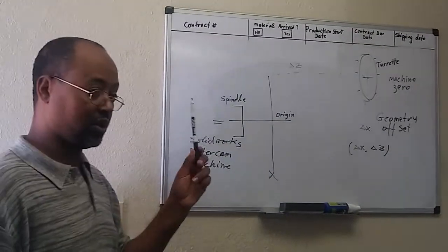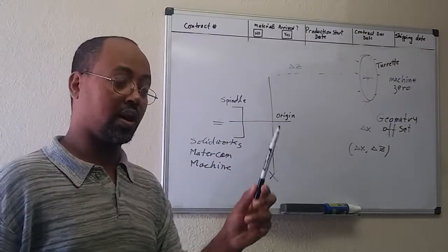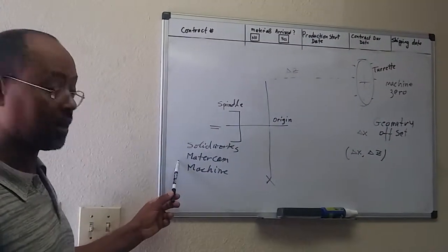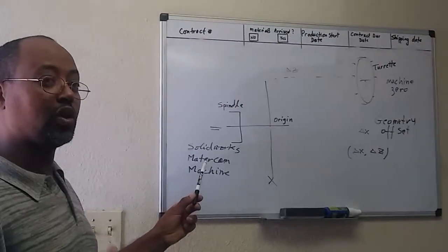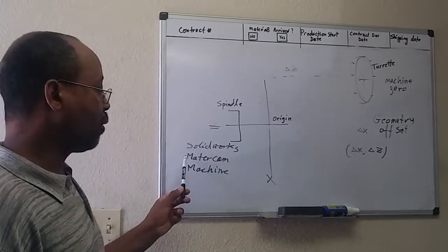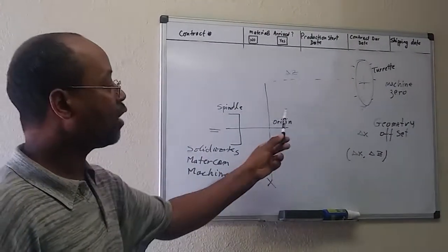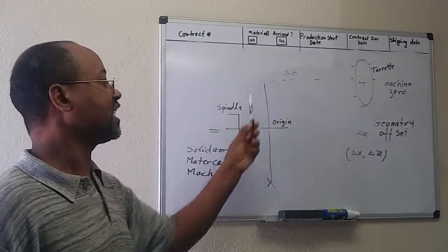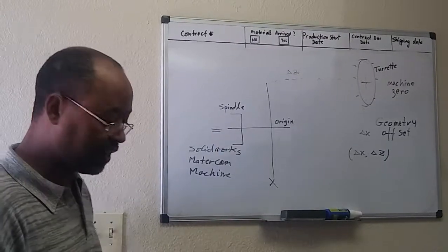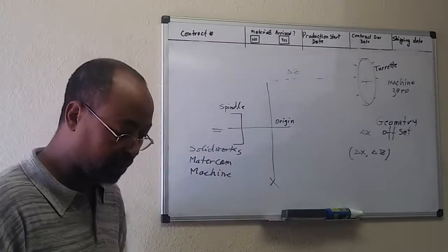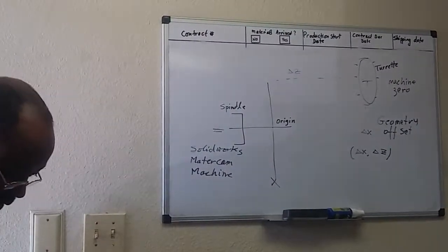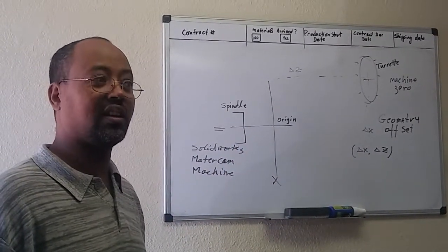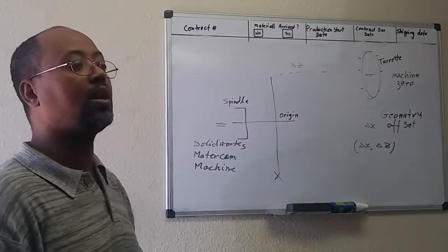Look what I just said. The question is, in your program, who gave me the program? Mastercam. The program that you're looking at for your part, that was given by Mastercam following all the different tool paths, what do you think is the value of Z in the program? Because Z has numerous numbers within the program. And all of them, you look at them, do you think you should see a positive Z or a negative Z? Negative. Thank you. It's all going to be negative.